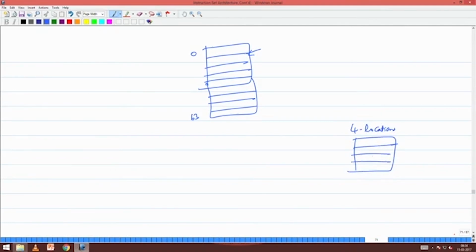First I assume I will not look at blocks now. I am bringing 1 byte. My block size is just 1 byte, just for our initial understanding. Later we will increase it to several bytes. So I need to have a mapping mechanism. What I do is, this is 6 bits and this is 2 bits. Let me call these 6 bits B5, B4, B3, B2, B1, B0.